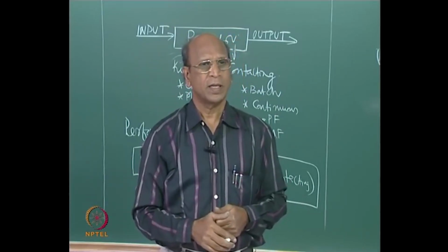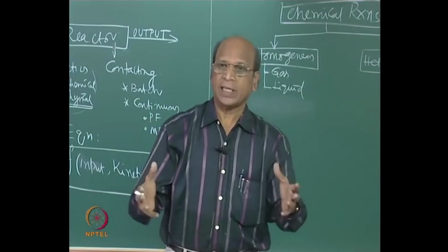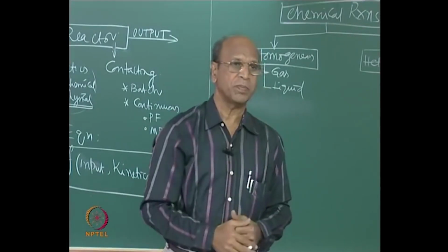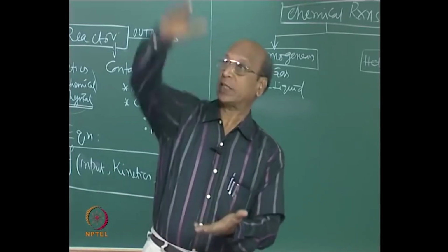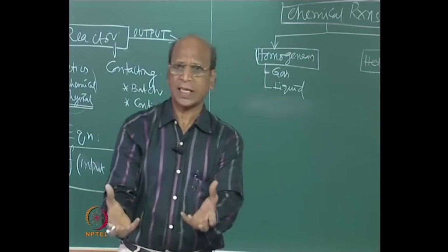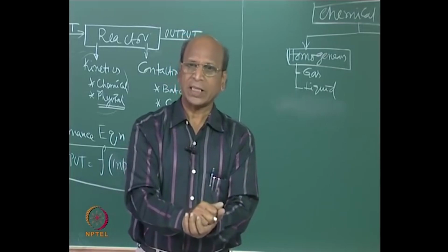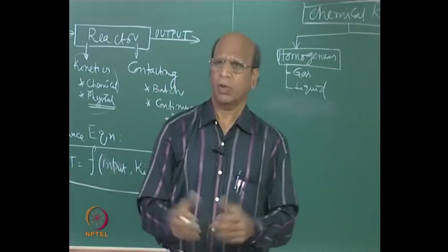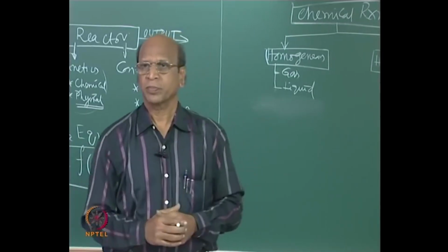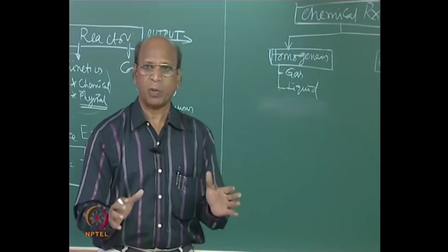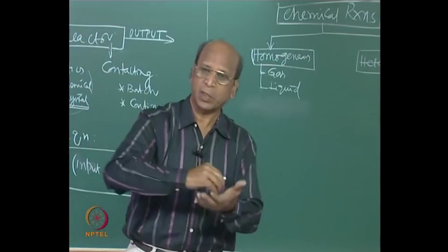Why should I worry? Because in industry, in one reactor you will have 2 tons, 3 tons of catalyst, and the bottommost layer should also withstand that entire weight. It has to carry that entire weight. So, if it is not able to carry, what will happen? It will crush. When it is crushing, you will have fine powder. It is good, when it becomes fine powder, you will get very good surface area. But the problem is that it will block all the pores.